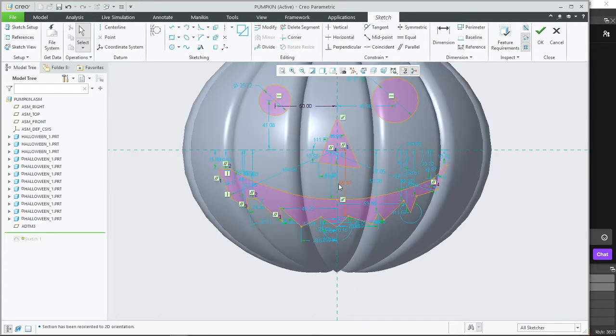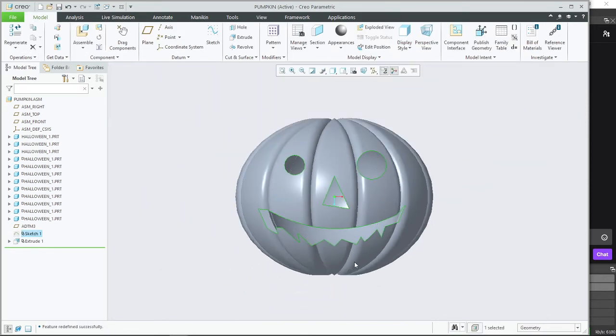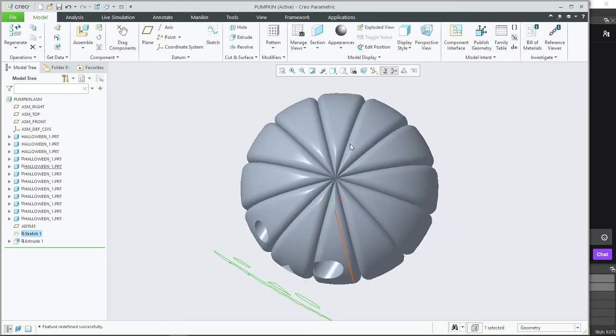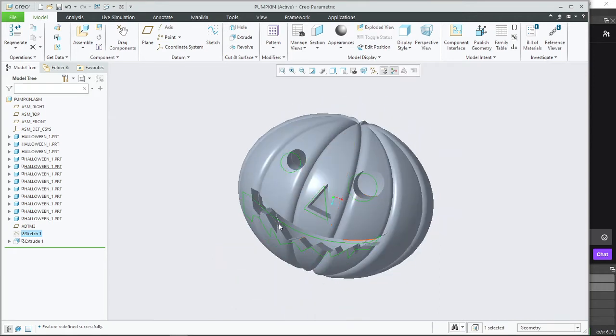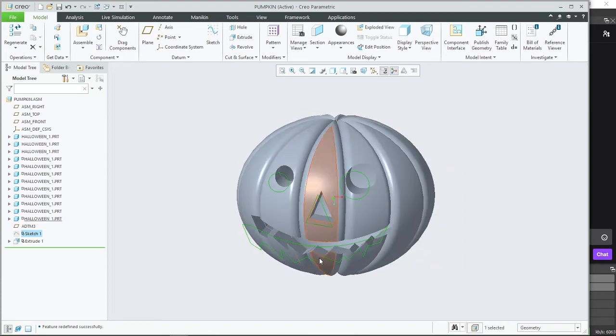And roughly. If I had been paying more attention to all these references while drawing, this wouldn't have happened. The only reason this happened is because when I decided to either check the positioning of one of the slices or change the hollowness of it, I probably changed one of the parameters one of these lines was attached to.